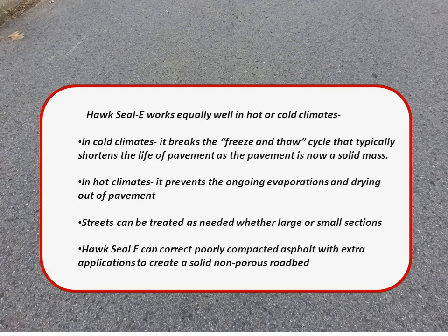The engineers from Hawkseal were called to see what they could do with it or recommend as engineers, and they decided to treat it with Hawkseal to see if they could fill those voids and fissures. It took 8 applications to saturate and fill that poorly compacted pavement, but it is still in place now, approximately 15 years later.